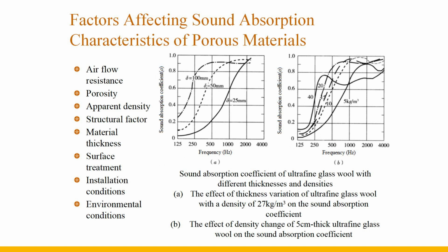It shows that the perforated plate and the membrane can be combined with porous material to form a composite sound-absorbing structure. The surface of the finished structure can be decorated, but care should be taken to avoid the water-based paint closing the pores, and it is not suitable to use paint.